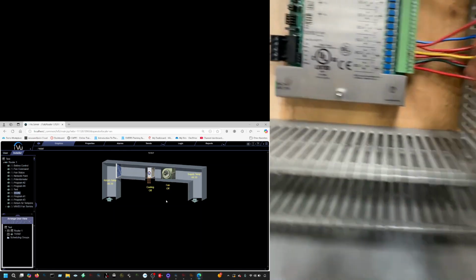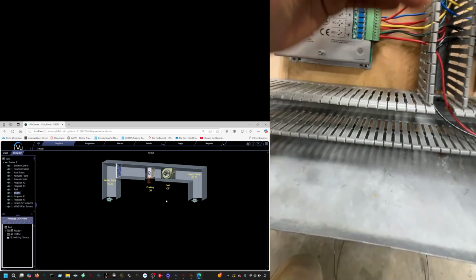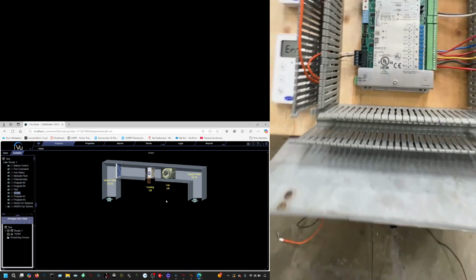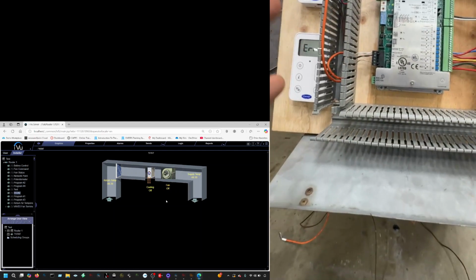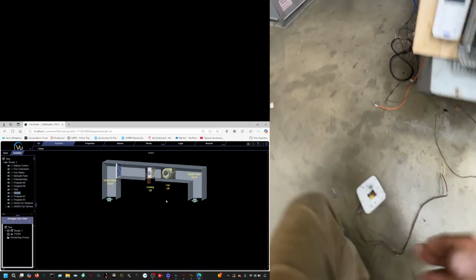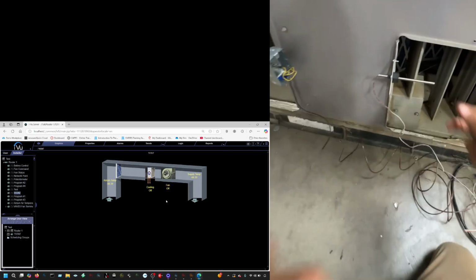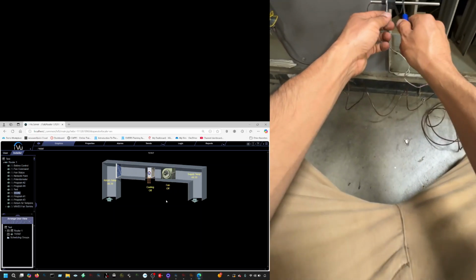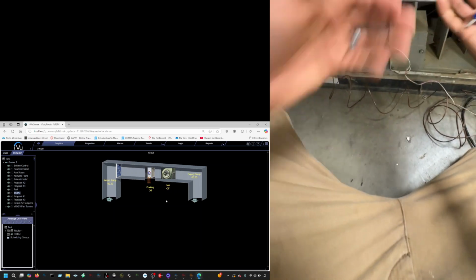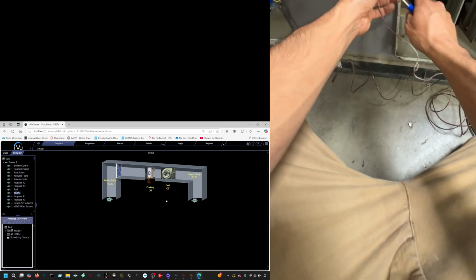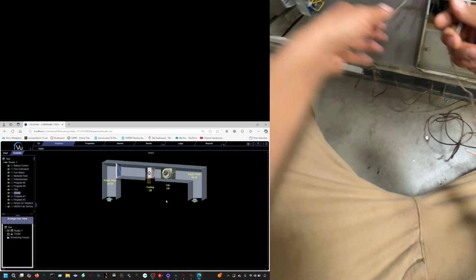Okay, so that's done. The binary outputs, your switches, that's down here. So because we're not using a thermostat, we need to be able to read temperature. So right here, I have thermistors, 10K type 2 thermistors. It's just a special tubing. They're temperature sensitive resistors, and they have 2 wires coming out.